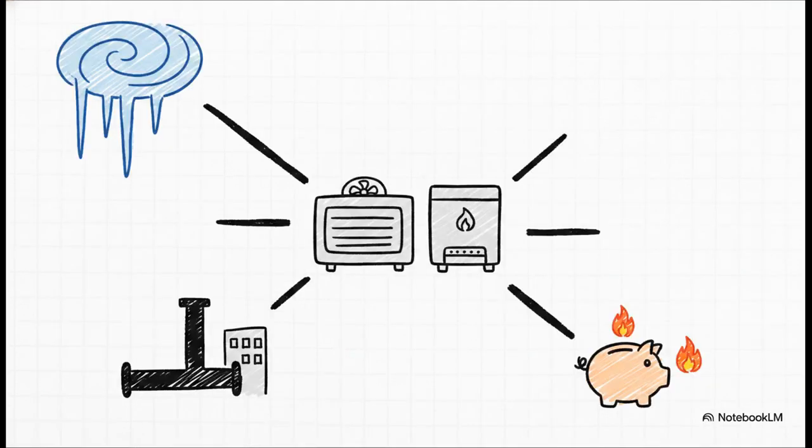Finally, what about the classic combo? When should you pair an air conditioner with a traditional gas furnace? This setup is still the heavyweight champion if you're battling harsh, sustained cold climates where heat pumps tend to struggle. It is also incredibly practical if your building already has existing gas infrastructure piped in, and if your local natural gas utilities are relatively inexpensive compared to electricity. In those specific scenarios, this dual combo is almost always cheaper to operate in the long run.